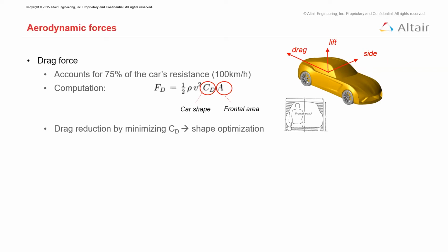The frontal area, as you see pictured here, typically in automotive cases, we're going to be using the frontal area, and that's just taking a cross-section view from a front perspective and plugging that area in right there. If you're working on an aircraft, for example, you're going to want the planform view. That's a top-down view looking at the wings. In some simple cases, you're actually going to want to use the wetted area, the total surface area of your model. But that's only in cases where you know it will be a pure laminar flow. So in 90% of the cases, I would say you want to use frontal area.